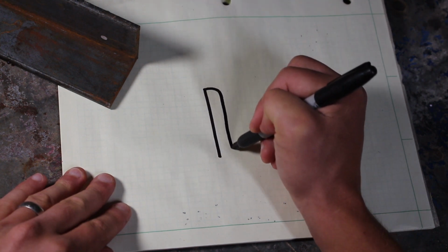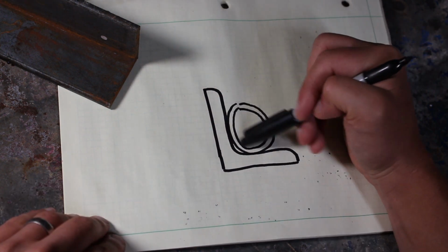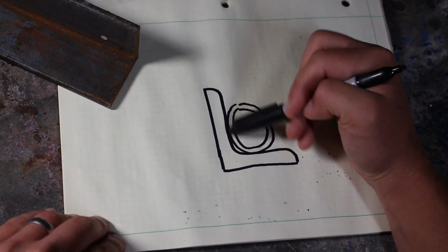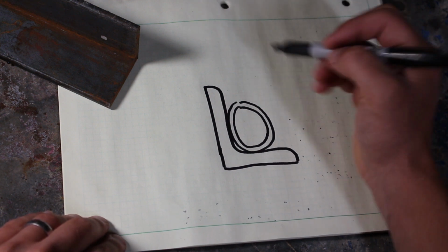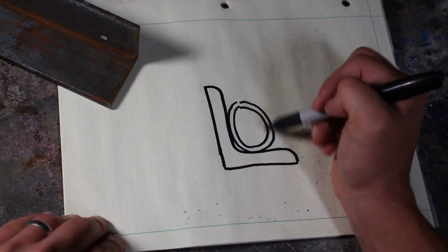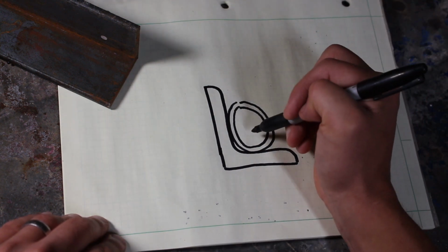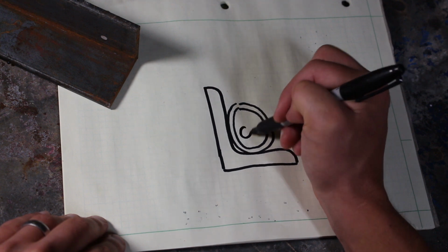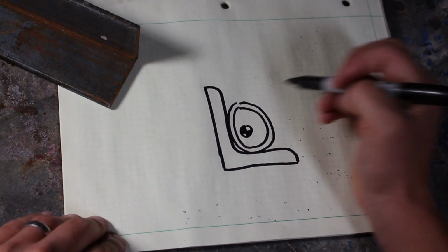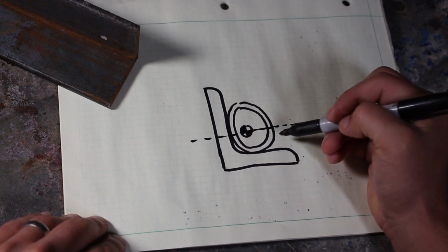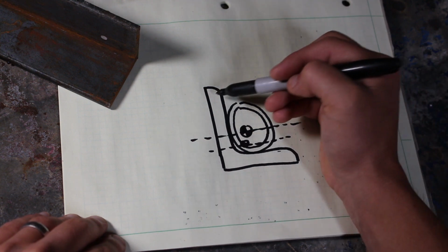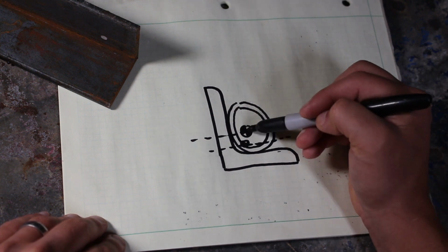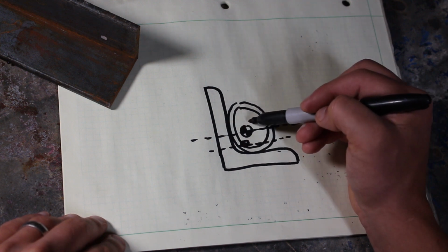Now, a couple comments. Really, our shape looks something like this after the legs are sistered. But because I had to reform this tube component that we analyzed in the other video, I want to be conservative, and I can't count on it taking any of the load, and so I'm looking only at the angle iron. You could do a compound shape analysis, and your cross-section would have a centroid maybe somewhere up here. And you would basically do the same analysis that we just did, but you would have to use another set of parallel axis theorem equations to figure out the contribution of the resistance to bending of the angle to the overall compound shape cross-section, and do the same thing with the tube.